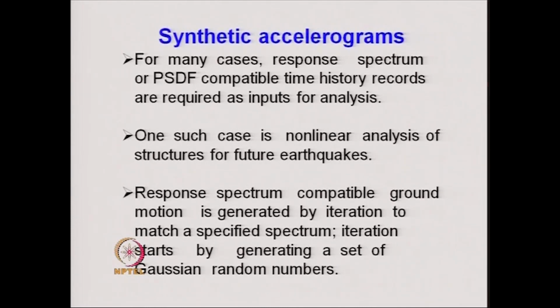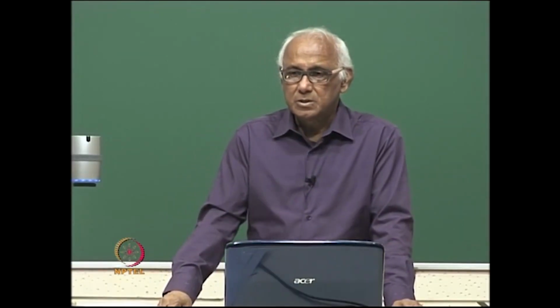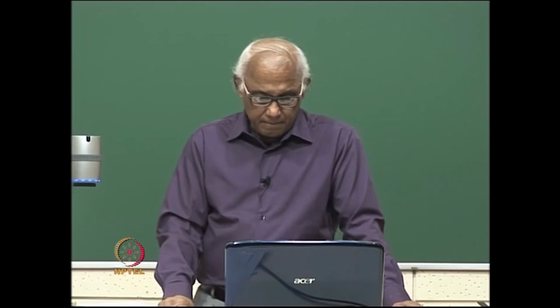These time history records, which are generated from the given response spectrum or given power spectral density function, if they are used for constructing back the response spectrum or power spectral density function, will be the same as the ones from which they were generated.